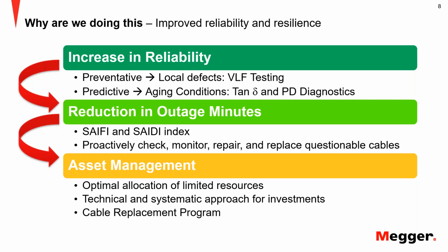So, spending it on cables, judging the cables by age, installation date, has not proven to be very good. And throwing dice is also not a solution. So they want a scientific, a technical approach, right? And all of this preventive and predictive testing is pretty much the base for the asset management to then make a decision and to do their risk assessment.